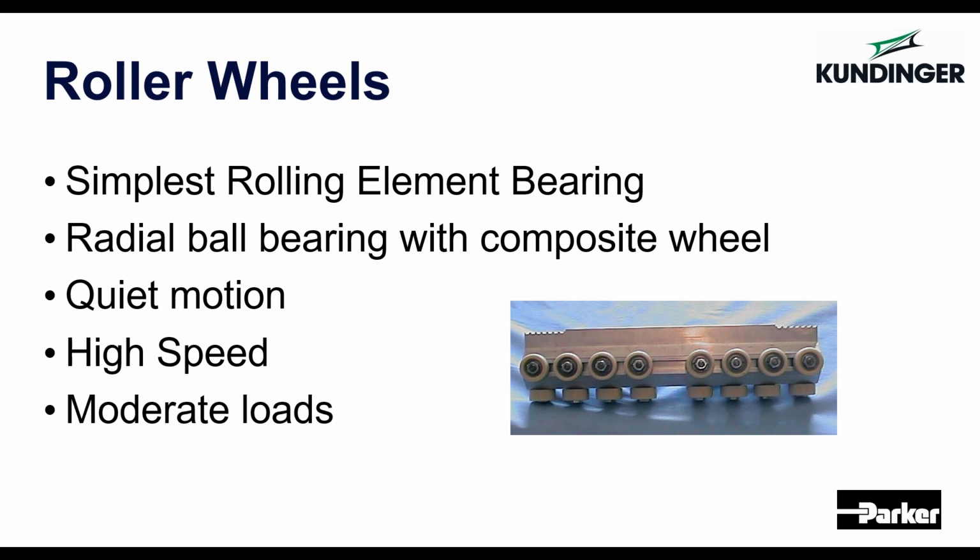We're not worrying about how long we can get a square rail manufactured and how long we can align that rail. Pretty good for moderate loads as well, but this is still an elastomeric element, so you do potentially have some stiffness concerns. And with any bearing, you are susceptible to skidding if acceleration is too high, at which point you'll start wearing flats on your wheels and eventually start locking the actuator up.